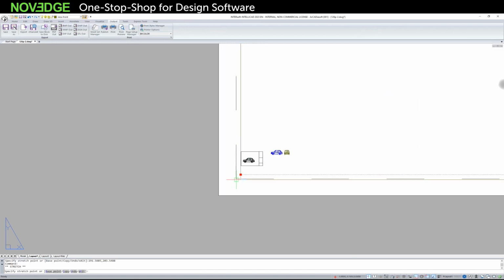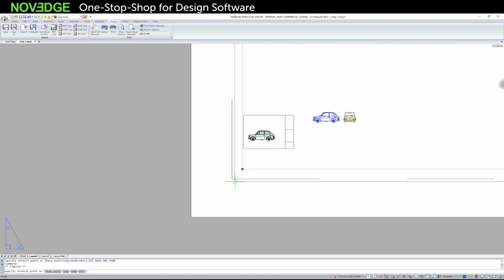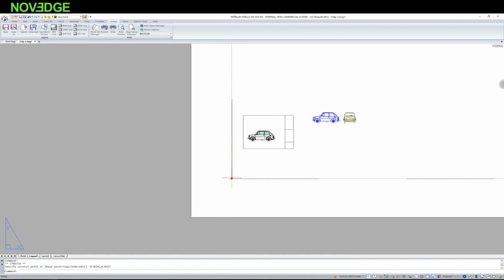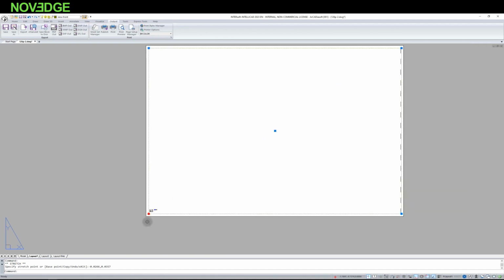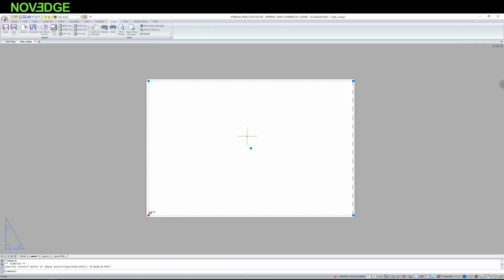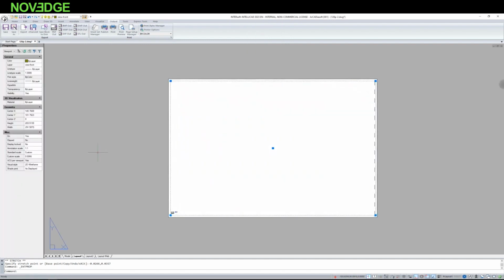Please note that the snap points do not work here. It moved a bit here, but only because I had this one defined here before. Now please note the snap points do not work. When I had the sheet inserted here, of course, this format moved to what already existed, so it obscured the drawing a bit. To be precise, I should right-click, go to the Properties, and in Properties define the size of the sheet. Here on the left, I have the height, which is A4 format, so 210 by 297.